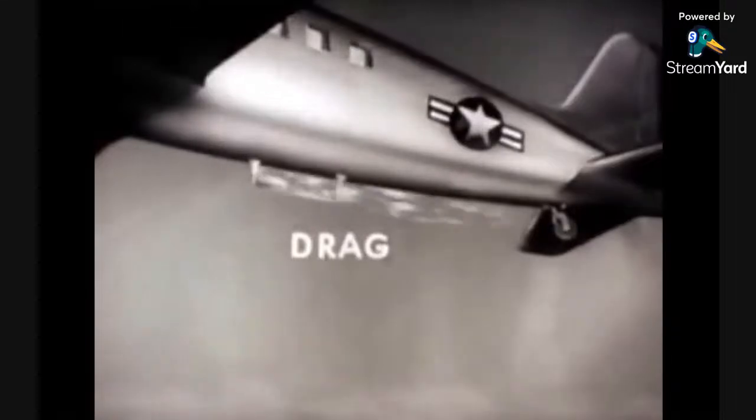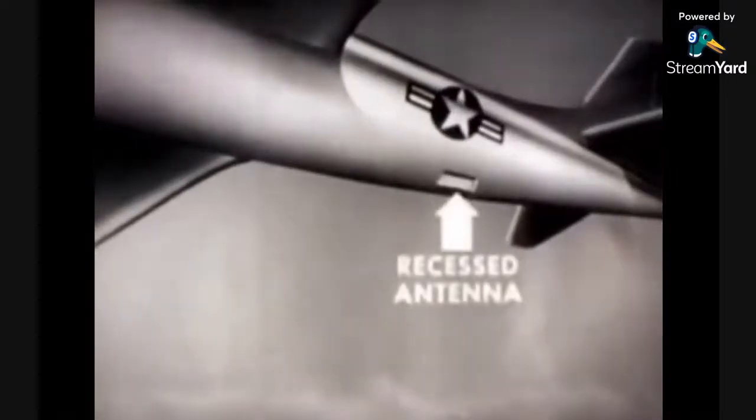But this wire antenna causes drag. Therefore, on high-speed aircraft, the antenna system is recessed. Generally, it is located between the wing and tail assemblies and is shaped like an inverted miniature bathtub. The receptacle acts as a reflector, concentrating a greater amount of energy toward the antenna rod. The reception pattern is still like a teardrop, but more directive, sharper than the old-time outside-underside wire.